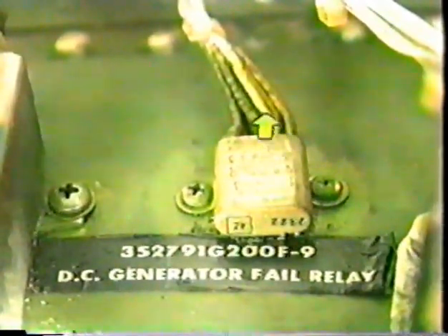Follow this wire through the generator fail relay to the non-essential bus switch. With the switch in the normal position, continue the wire trace to X1 on the non-essential bus relay. This puts controlling power at the non-essential bus relay. At this point, the relay will close, so long as a good ground exists at X2 on the non-essential bus relay.